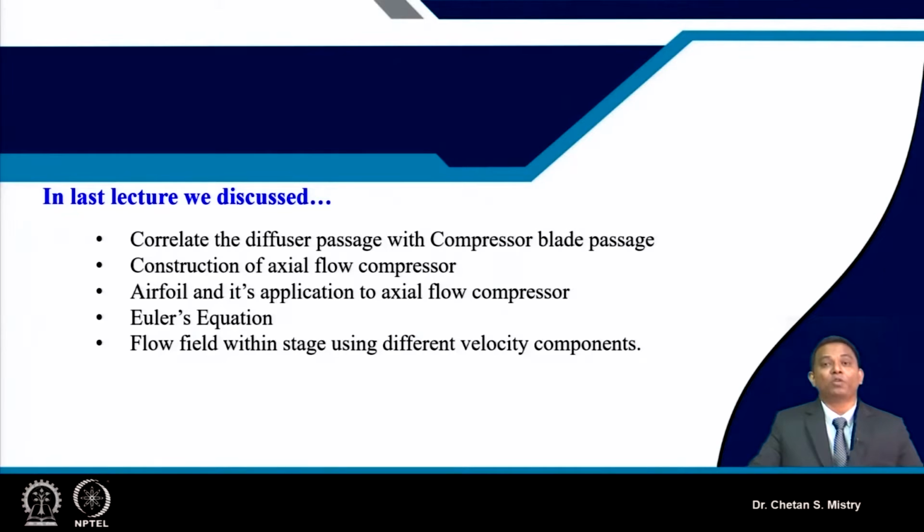Many times people bend a plate and also consider that a blade. Yes, that can be used as a blade for making a fan, but just realize what pressure rise we are expecting, which is large. For a curved blade, that pressure rise will not be achieved as per our expectation.